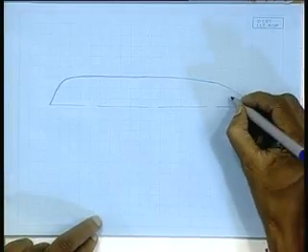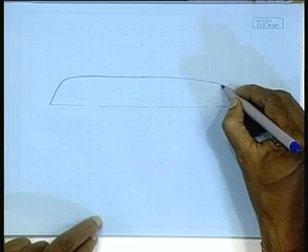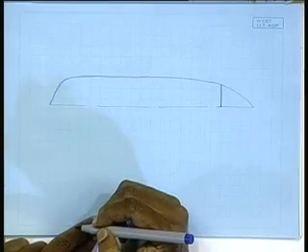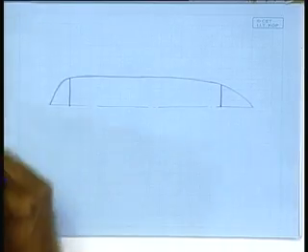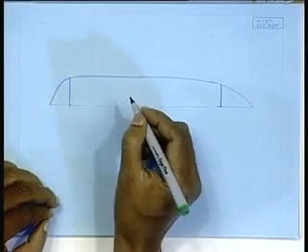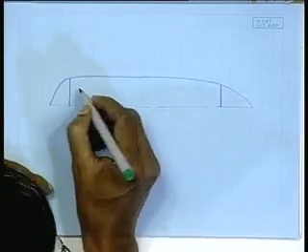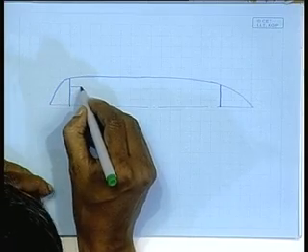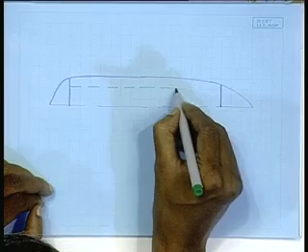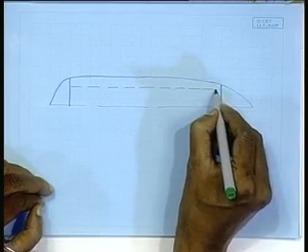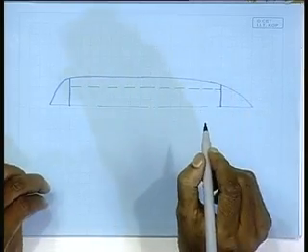Let us assume my forward peak bulkhead is somewhere here, right? After peak bulkhead is somewhere here, and let us draw only one or two longitudinals, just because no point drawing all. And why I am drawing longitudinal, not transverses, because I said that it is a wise thing to do is to provide longitudinal stiffening arrangement, because that gives you better buckling strength.